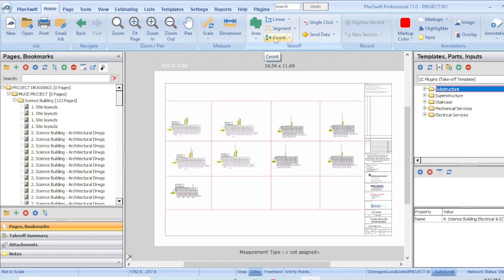When you're doing measurements, we measure work items in square meter, in linear meter, in numbers, in cubic meter. These are the functions. If you need area measurement, this is the function. If it is a linear measurement, or counting, this is the function. This one is not commonly used; you can just use it occasionally.